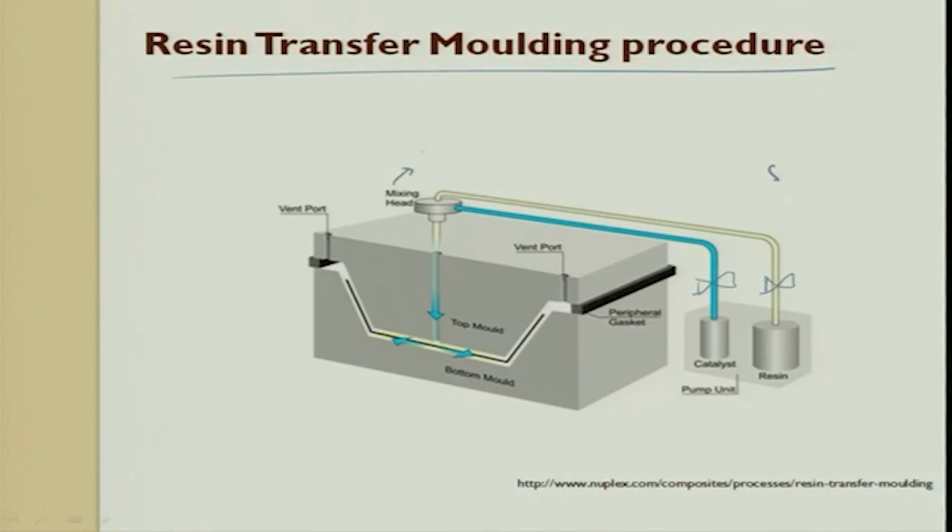So, this is a challenge because resin is highly viscous. If it is light, or if it is comparable with water, then mixing becomes easy. So, then what you have to do is, sometimes apply heat to the resin to change the viscosity, so that when it goes here and when the catalyst is added, it can be uniformly mixed.